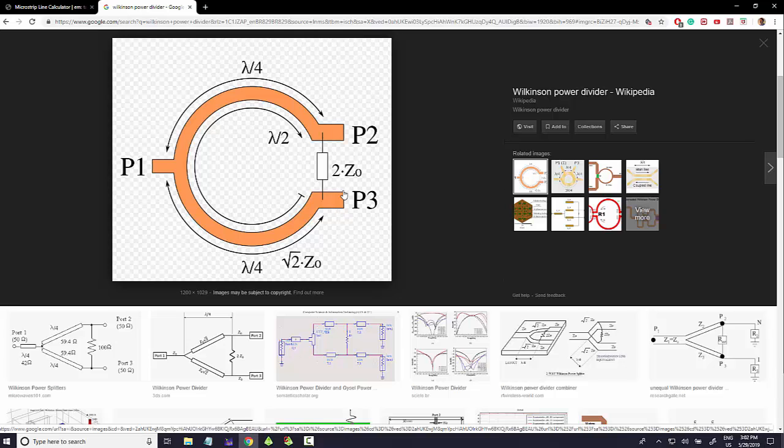What I mean is, imagine that you have a generator here, and you have 2 antennas, one antenna here and one antenna here. I have to be sure that there is no communication between the antenna over here and the antenna over here. That means that the isolation between these two ports should be as high as possible. So this part here doesn't feel what happens here. So even if I short circuit P2, P3 should be working in a normal way.